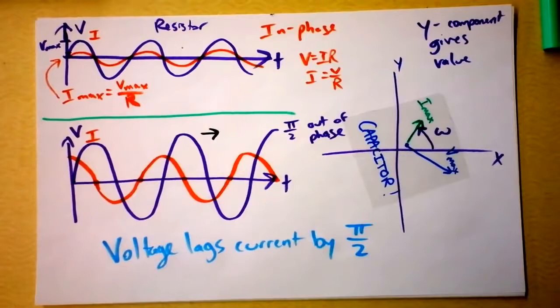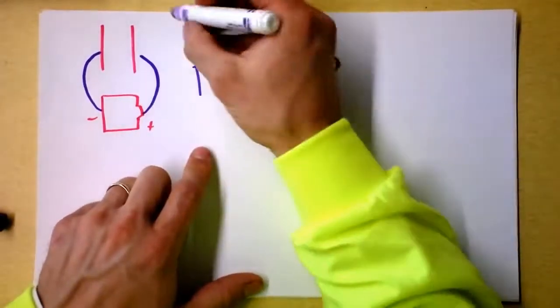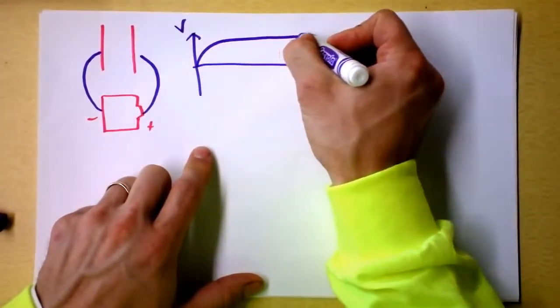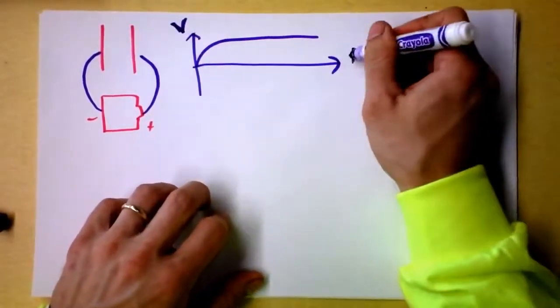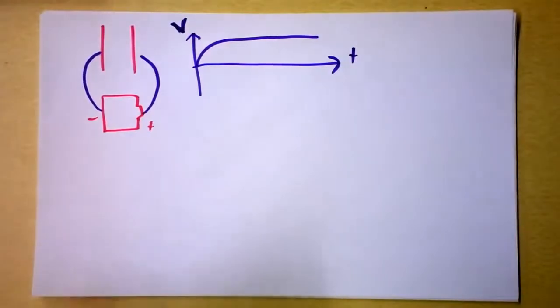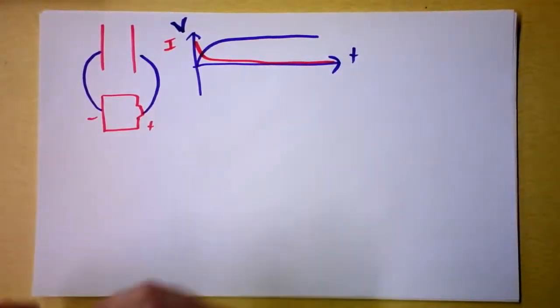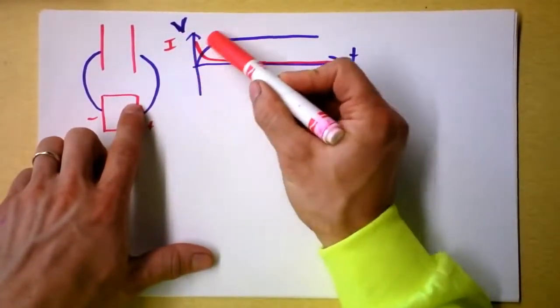Connect that, see? As soon as I connect that, the voltage on the capacitor will gradually increase like this. Voltage will go whoop, like this and approach some maximum level, probably the voltage of the battery, if this is a function of time. But I also want to know what the current in this circuit is going to be: falling to 0, and the voltage will be rising up.